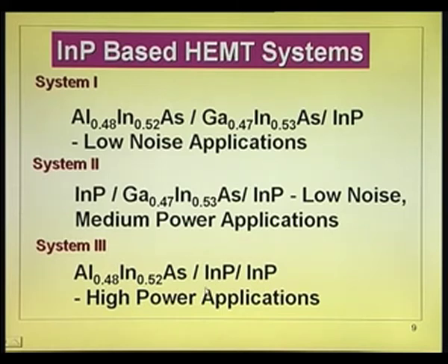Okay. Now, you can see you still get a delta EC between these two of about 0.3, because see, this is 1.46 Eg, this is 1.35. If you use your formula blindly, you will get 1.46 minus 1.35, 0.1, divided by something, less than 0.1, but you get about 0.3. This is because the neutral level of indium phosphide is 1/3 below the conduction band. I have given you enough food for thought to work out these numbers.